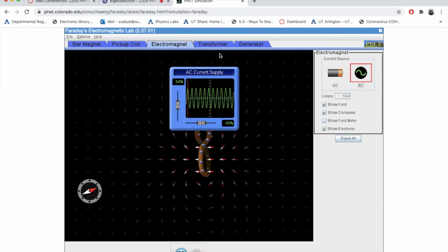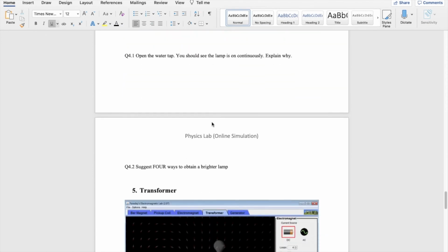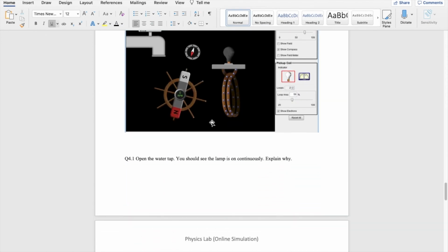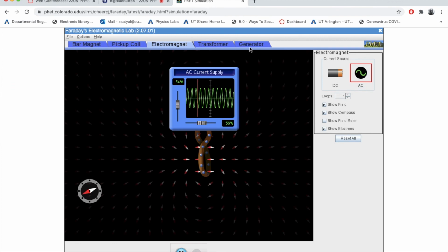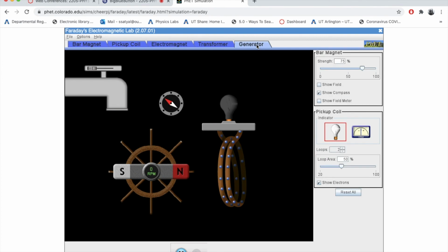And so next, let's move on to the, I believe next is the generator, electric generator. So we're just applying what we have learned on electromagnetic induction. We said we can change the area or the angle of it. We can change the angle of rotation of the coil, which changes the flux going through the area, and that in turn induces current in the coil.